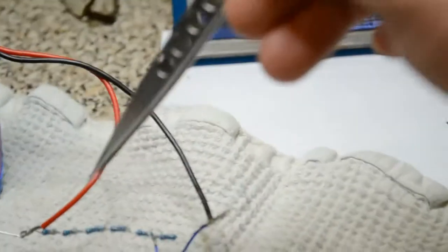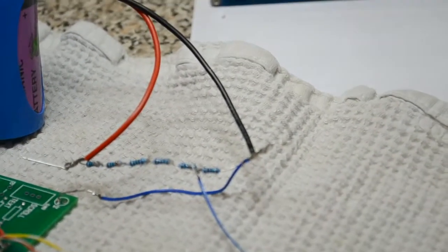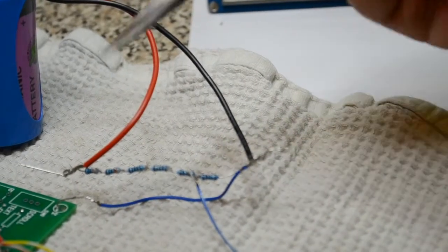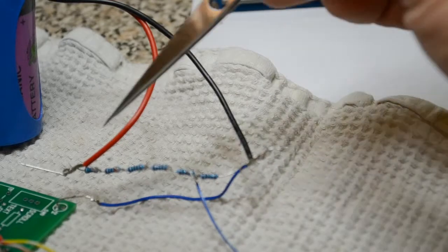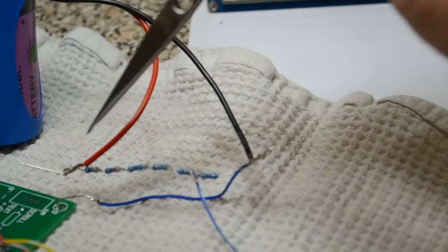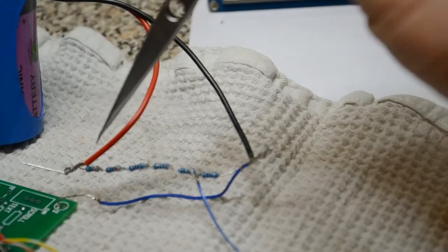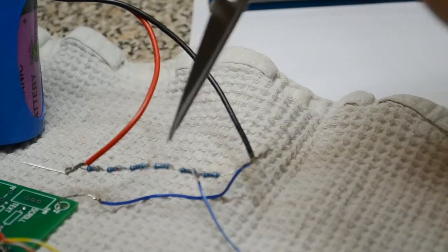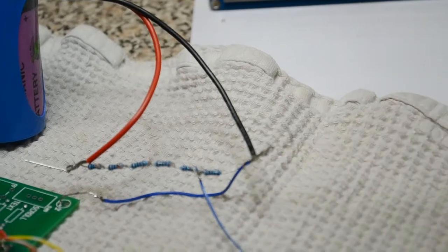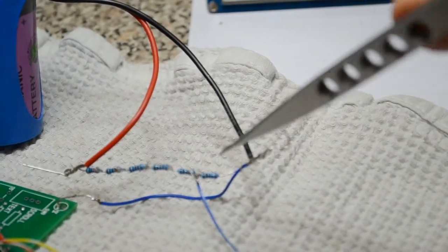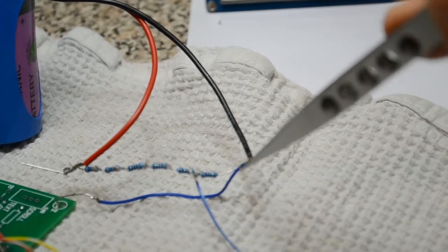I've got that running to this voltage divider, which is actually made up of 6 1K resistors. I could have used a 5K and a 1K, but I haven't got a 5K, so it's got to be equal values, or in this case it does for simplicity. So I've got 6 1K resistors in series, and you'll see, so that's 10.8 volts there, and ground is here.